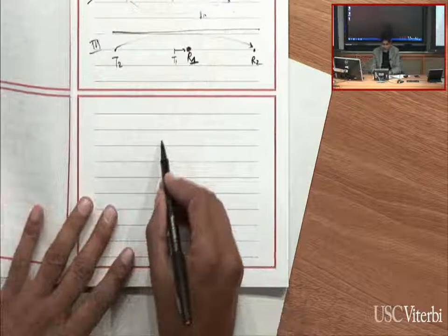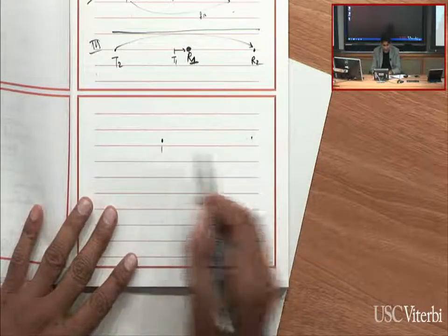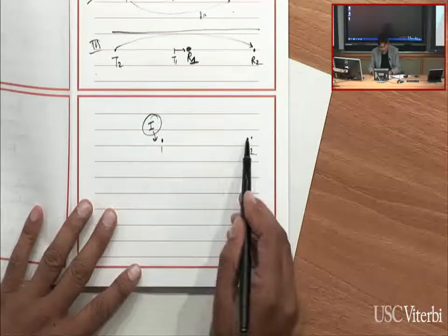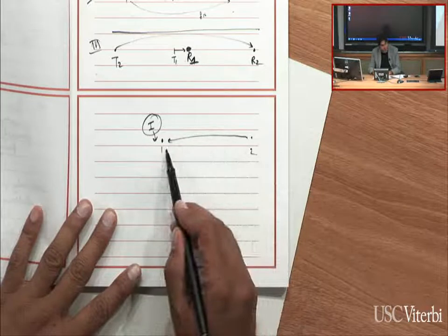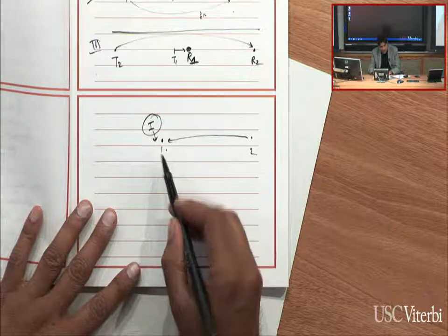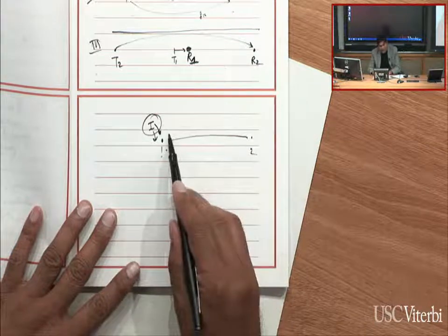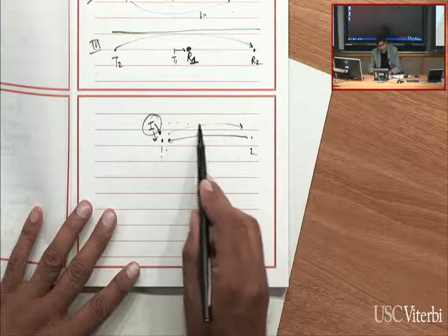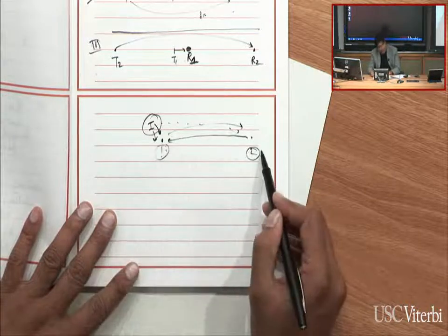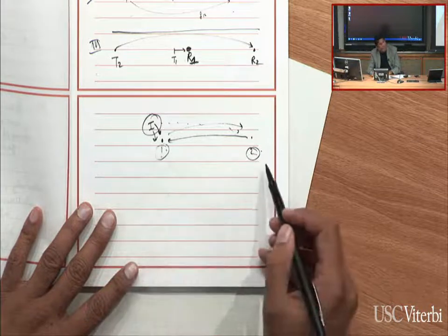And the scenario there is you have 2 links. Let's just call them 1 and 2. And then there's a heavy interference source close to 1. The signal coming from 2 to 1 is received with a certain strength, but at this node, the interference is also very high. Whereas in the other direction, the signal might actually beat the amount of interference coming from here. Right? And so the SINR at 2 might be higher than the SINR at 1. So in that situation, 1 is able to decode, but 2 is not.